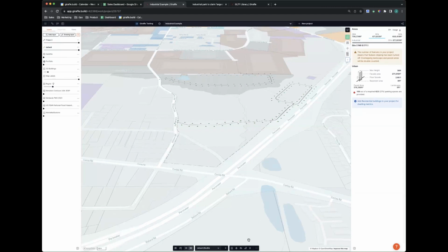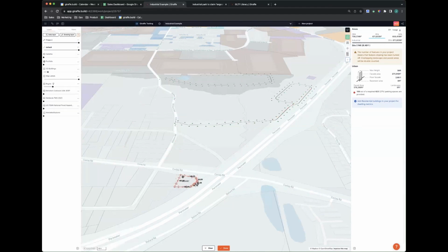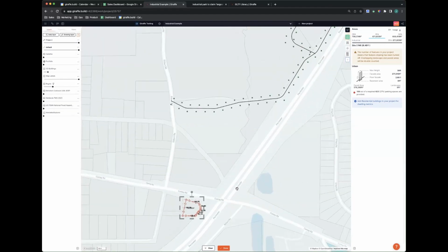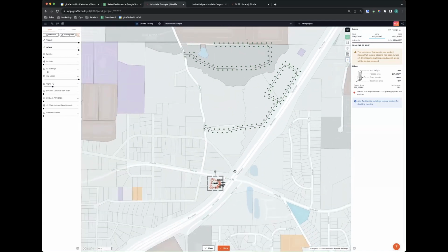of the site. So we need to be in edit boundary mode to do so. So if I hit down here, see, once I've saved a project, I don't have it up there anymore. I have to go down here to edit project boundary. So I hit edit project boundary, and I'm just going to turn it into this boundary over here to demonstrate my point. Big collections of parcels like this are always a bit more complicated.